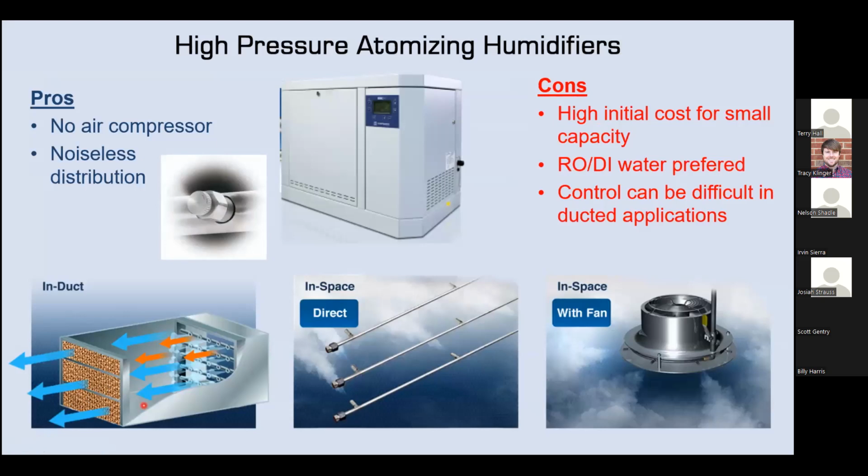So you might have a heating coil before that, and then a cooling coil after. This can all be calculated in our selection software to determine the preheat required to maintain a certain RH. This can also be sized just for cooling as well. The big benefit here is there's not much service. It's going to be basically on the pump.